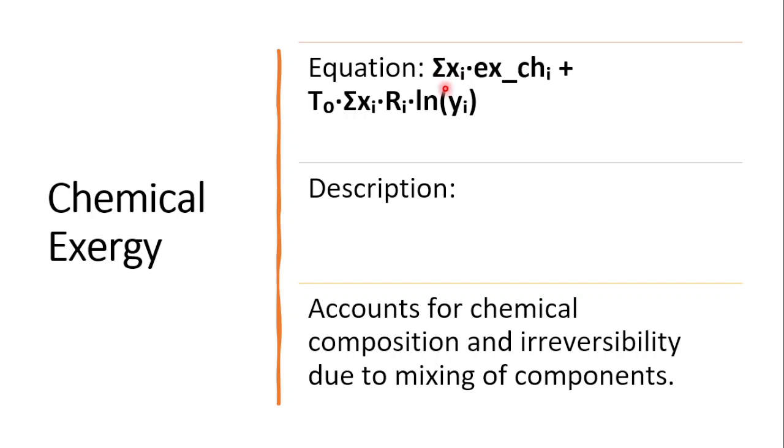x_i is the mass fraction, and h_i is related to the chemical exergy of formation, which can be found in several tables. T0 is related to the dead state, x_i is the mass fraction, R_i is the gas constant, and y_i is the molar fraction. The chemical exergy accounts for the chemical composition and also irreversibility due to mixing of the components.